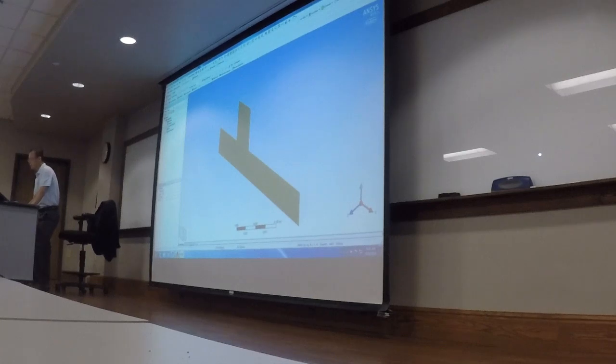Then hold down the middle mouse. Inlet. The rest of the surfaces, by default, is solid boundary. Yes, it is solid boundary. So that's this part. All right. Then click on mesh. Click on mesh, and what we're going to do is select this solid, and insert the sizing function.